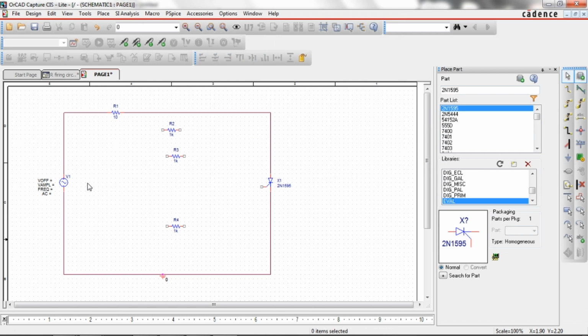Remember, always as an engineer we need to differentiate which is a power circuit and which is a firing circuit. See, this is your source, this is your load. The source is giving power to load through this switch. If there is no switch, what happens? Continuously it is giving power to load. I do not have any control. Here we have kept a switch. This is a semiconductor switch, correct? It is an SCR. If you apply a gate pulse to this, then only power goes from source to load. If you don't apply gate pulse, the power does not go from source to load.